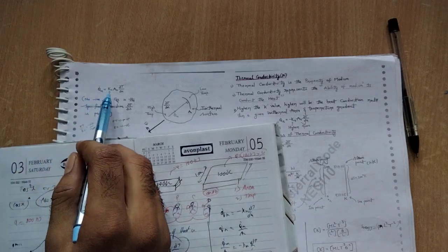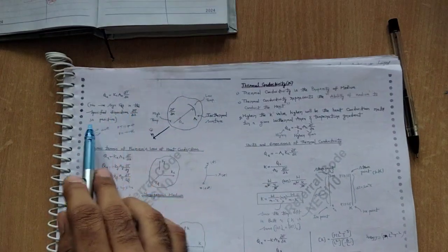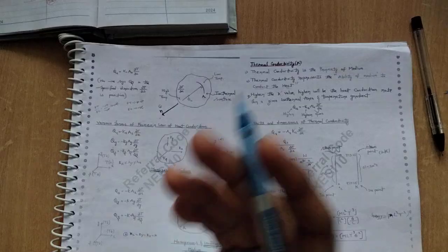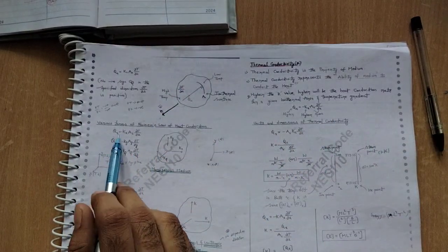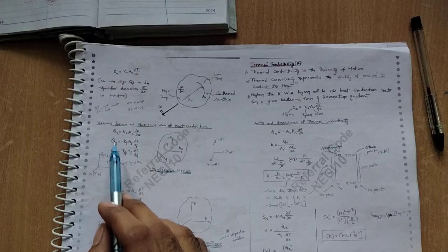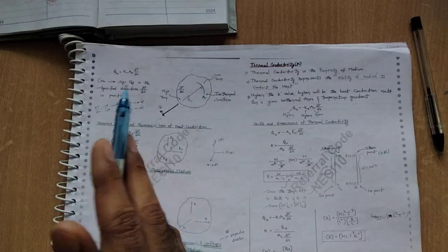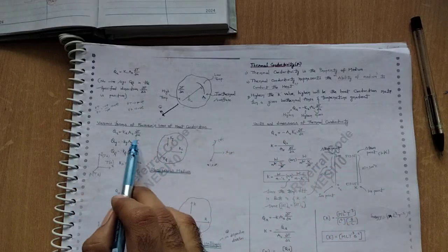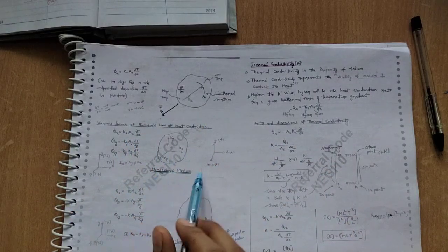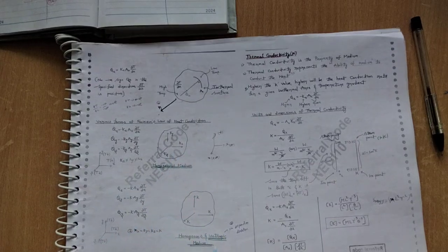So Q dot n equals minus K of n, A of n, dou T by dou n. Generally the direction is going outside, so no need to be confused. We have talked about a specific direction: x direction, y direction, z direction. So minus k of x, A of x, dou T by dou x. Here dou n is any particular direction, and we specify x, y, z, all three directions. We take a homogeneous medium, and isotropic.